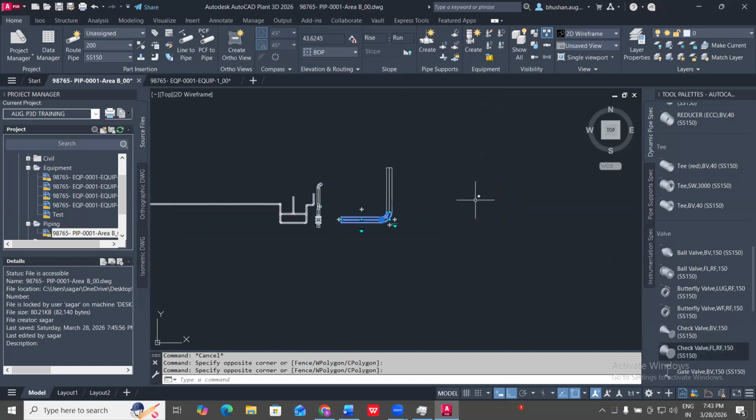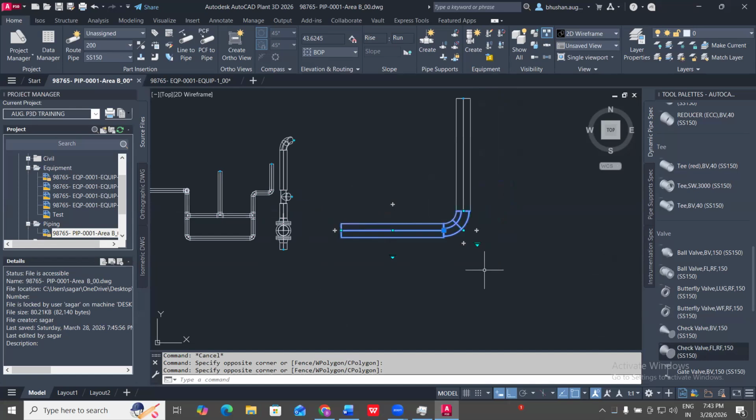In real life design, like what I have shown you here with the pipe, you often start with one type of fitting, like we can say a 90-degree long radius elbow, and later realize that a different type of fitting would be better. Maybe the engineer says use a short radius elbow, because there is not enough space, or maybe you routed the pipe with a standard elbow and they realize the spec actually requires a special elbow.